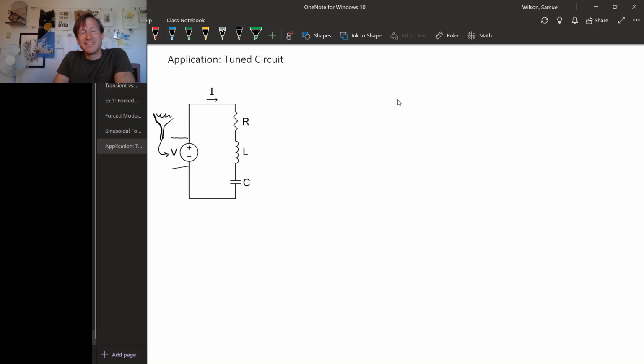What an antenna does is, the electromagnetic field of the radio waves hits the electrons in the wire in the antenna and makes them move around a little bit, and that generates a voltage. Typically that voltage is very small, and also typically that voltage is a mixture of many different frequencies. And somehow we need to arrange for this circuit to choose and amplify just one of those many frequencies. So to represent this situation, what we're going to do is write down a differential equation with a forcing function that has a particular form.